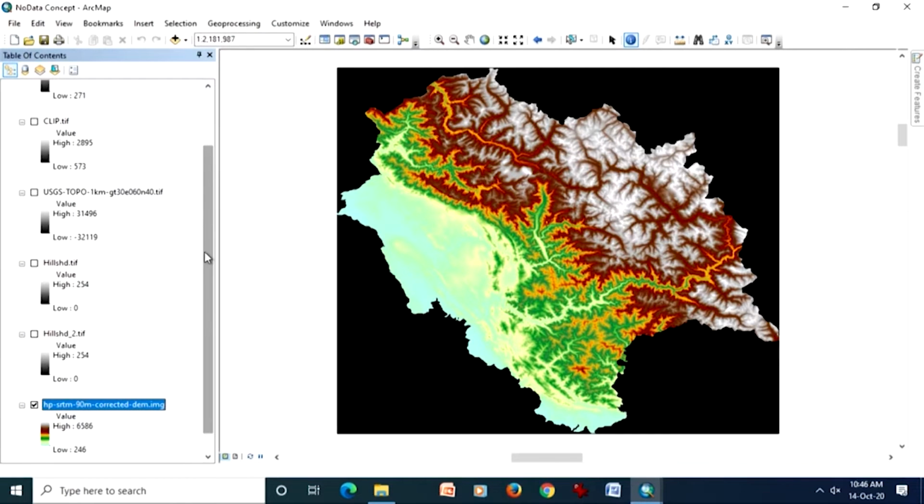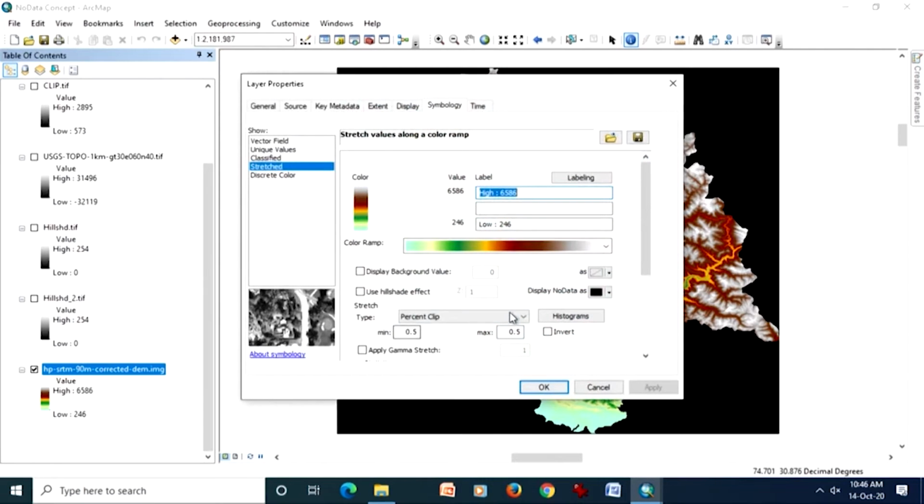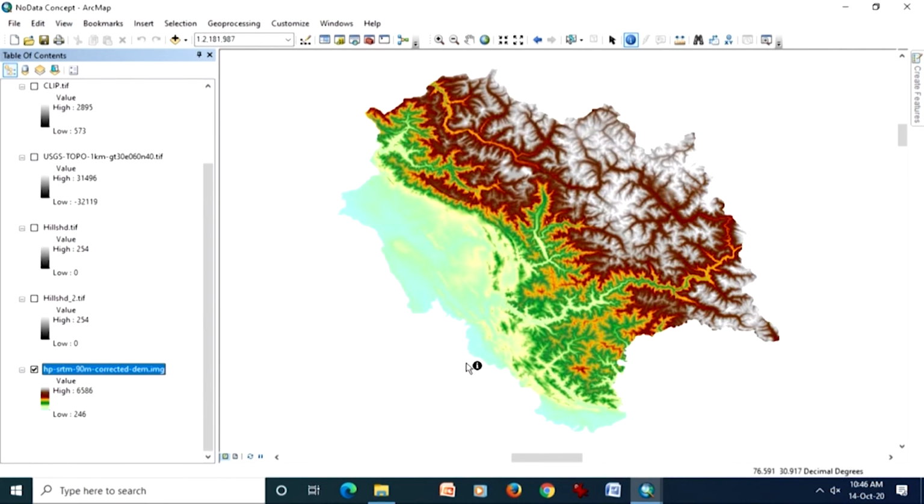But related with the no data, I would like to discuss this hillside. Here again this is a SRTM 90 meter digital elevation model of Himachal Pradesh. Again there is an arbitrary boundary, and the background, or the no data value, has a black color, which we can check also here. See, no data is a black color. Again if I choose no color, it will disappear, and it looks much more realistic and good now.